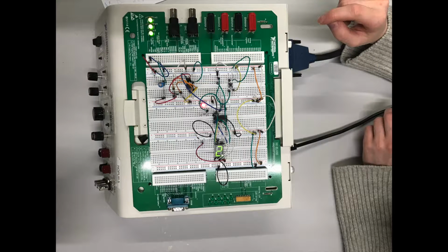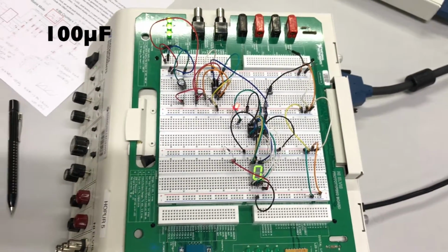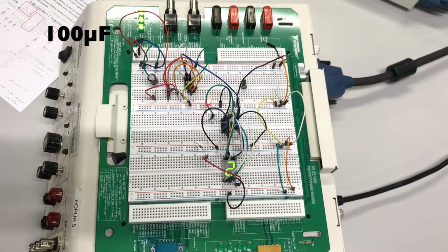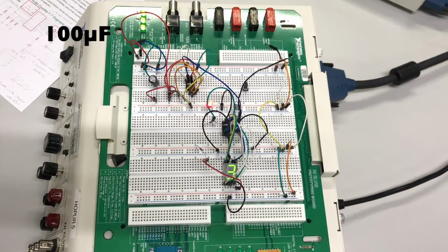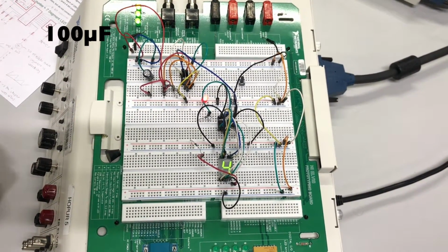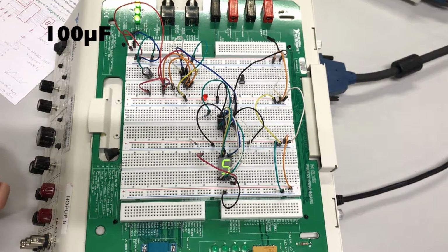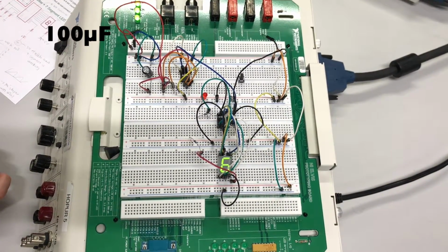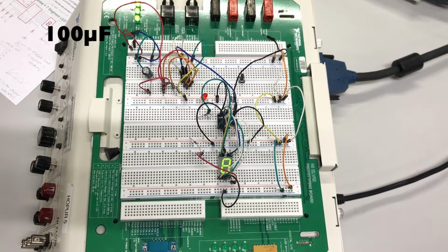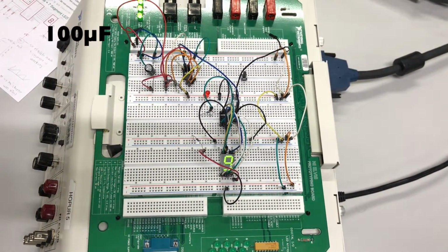IC pin connections were unknown, so we had to figure out which connection worked. By connecting the circuit in different ways, we found out that the clock is in pin 12, Q in pin 1, and Q next in pin 4. We had 6 different capacitors with various capacitance. By switching the capacitors in the circuit, we saw that the higher the capacitance is, the longer it takes the capacitor to charge, and therefore it takes longer to change the digit on the 7-segment display.